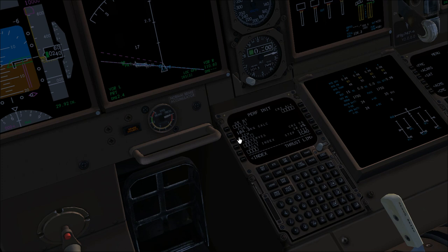Today we have 104 tons of fuel, just to get a good weight for the departure, and our zero fuel weight is 179.8 tons. We can select this in zero fuel weight, and we have the gross weight that is 284.1, exactly as expected. Reserves for today are more than 50. We will just select 50 as a dummy figure, and our cost index will be 150. You can select any cost index that is between 0 and 999.